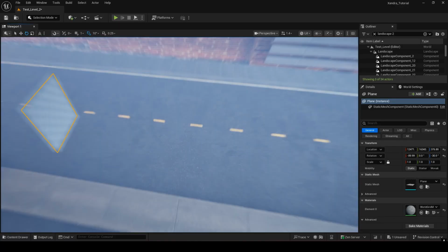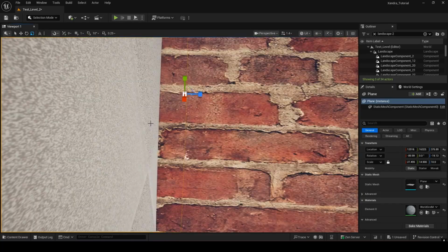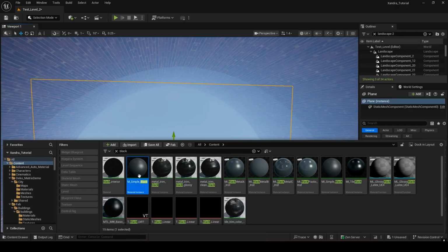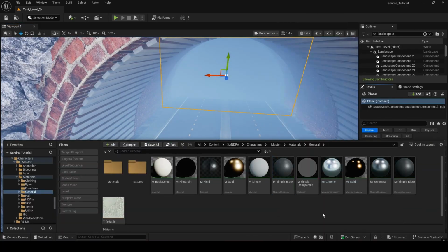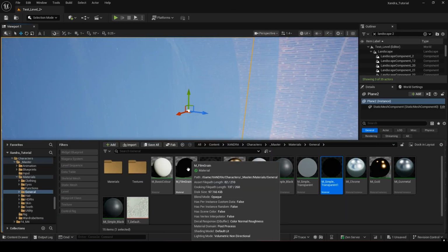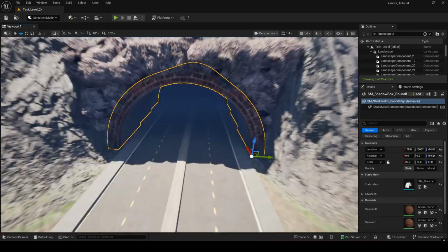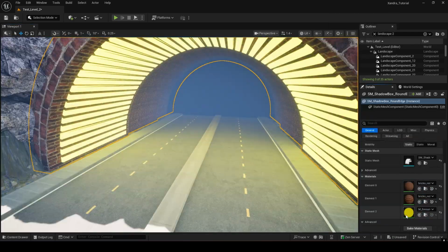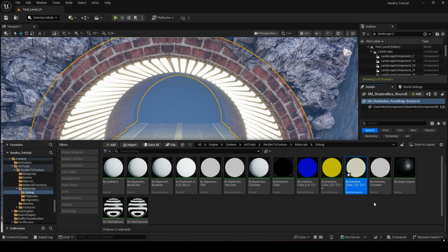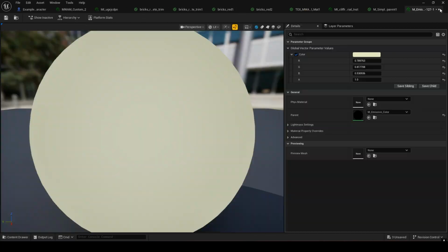And then next you're going to see me fiddle around for a little bit. I use 2 planes here. One with a straight up black material, and the second with a black material but with an opacity mask on it, so you can kind of see through it. That gives me this fade to black effect at the end of the tunnel, to hide the landscape behind it so it looks like it stretches off into the darkness. It's a quick, easy way to achieve that effect, just with those two planes.